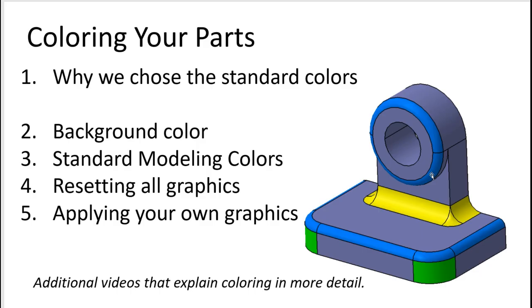So now we've talked about why we've chosen the standard colors. We've talked about setting the background to non-graduated, and we've talked about resetting the graphics properties and then how to apply all your own graphics properties.